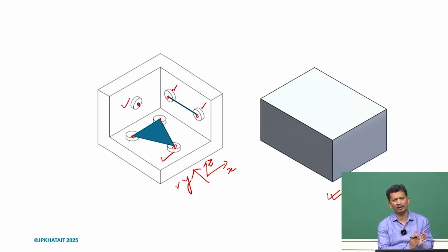So we have to understand location versus clamping. Bolts are used for clamping, to put the two parts together, but may not be for location. It cannot define the location properly. So we need to understand how to locate it properly so that certain objectives and specifications can be achieved.